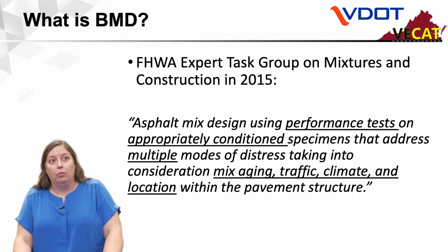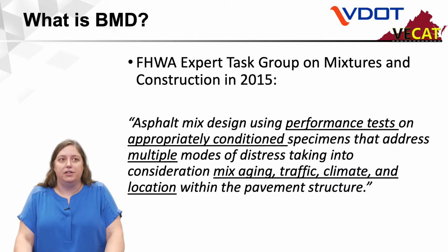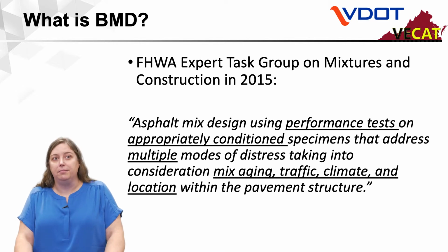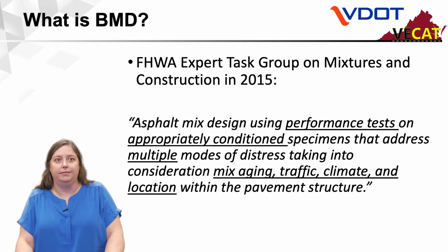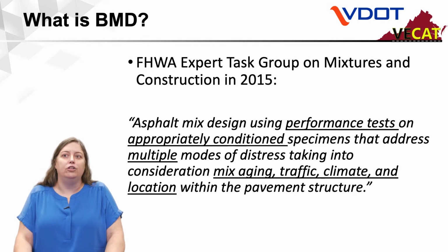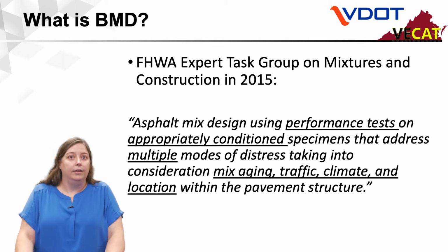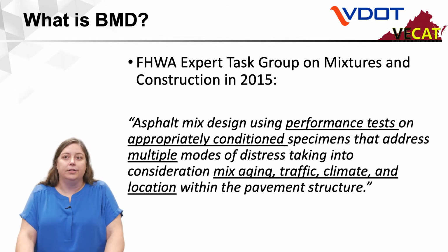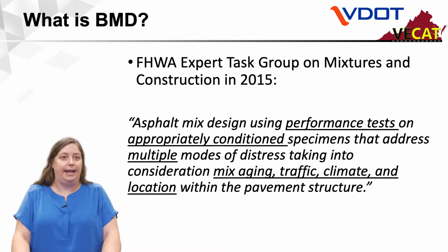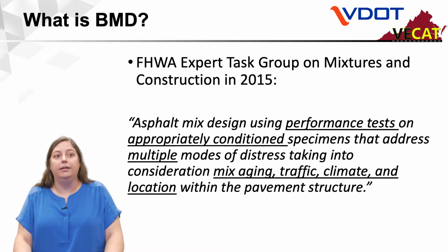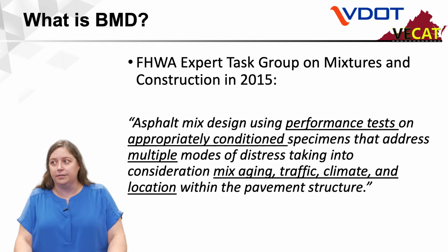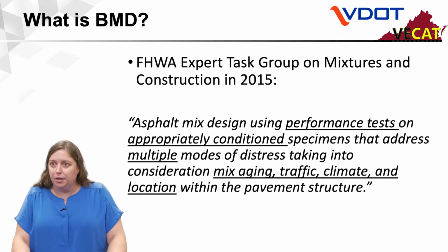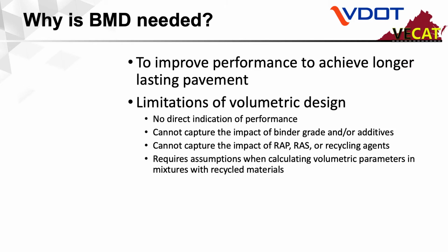First, what is BMD? A good definition is offered by the Federal Highway Administration's Expert Task Group on Mixtures and Constructions in 2015. Asphalt mix design using performance tests on appropriately conditioned specimens that address multiple modes of distress, taking into consideration not only mix aging, but traffic, climate, and location within the pavement structure. The idea is to design a mix for the right location with the right materials.